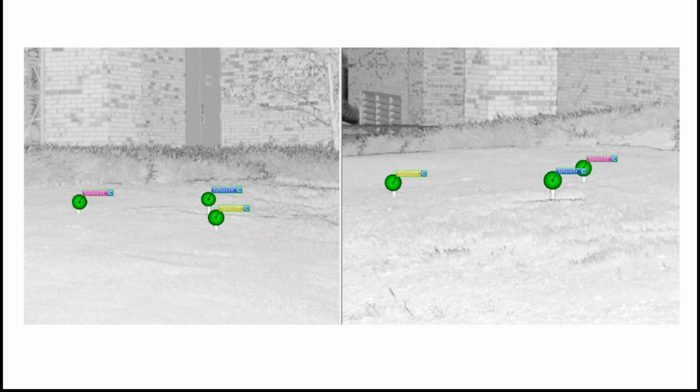You'll see they're colored green, so that means that there were enough points measured on those spheres from the point cloud that it could have a very good fit and determine that those are, in fact, 5-inch spheres. And then the software uses those 3 points right there to tie the 2 scans together.